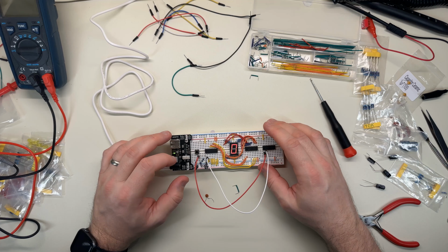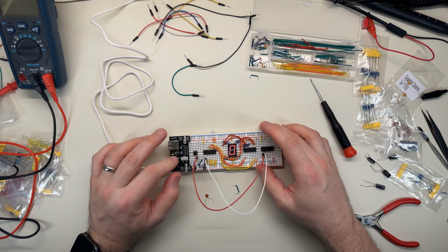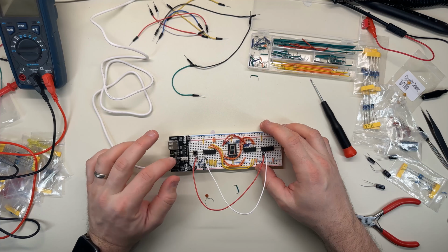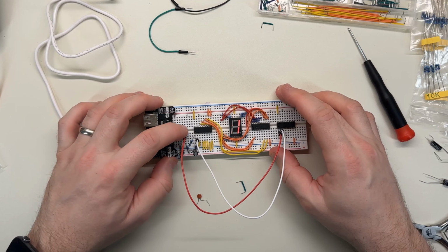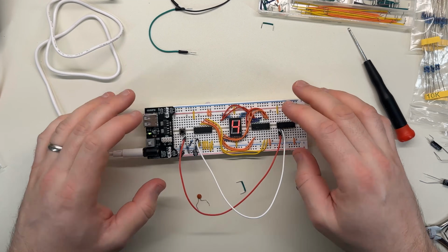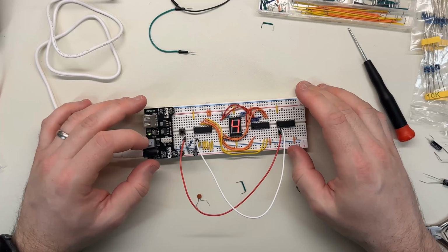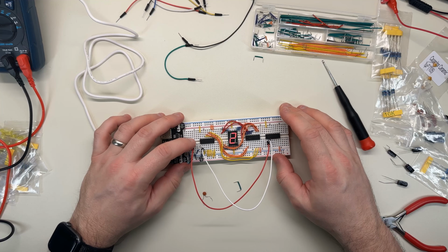And I don't know if I could turn this on and off that quickly anyway because of the physical switch here. So let's see. Okay, that's looking pretty good. And the counter still works because once the capacitor is fully charged, that pulls the pin high, which disables the reset and allows everything else to work. So hey, I'm pretty happy with this.